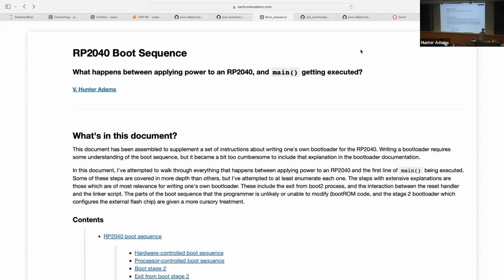I'm doing this for a couple of reasons. One, I think it's kind of interesting. And the second reason is that a couple of groups are doing projects for which it would perhaps be a stretch goal to implement a custom bootloader. So let me just remind you for context, a bootloader is the program that allows for you to load other programs onto the microcontroller. The RP2040, of course, like all other microcontrollers, ships with a baked-in bootloader so that we can actually program it when it arrives.